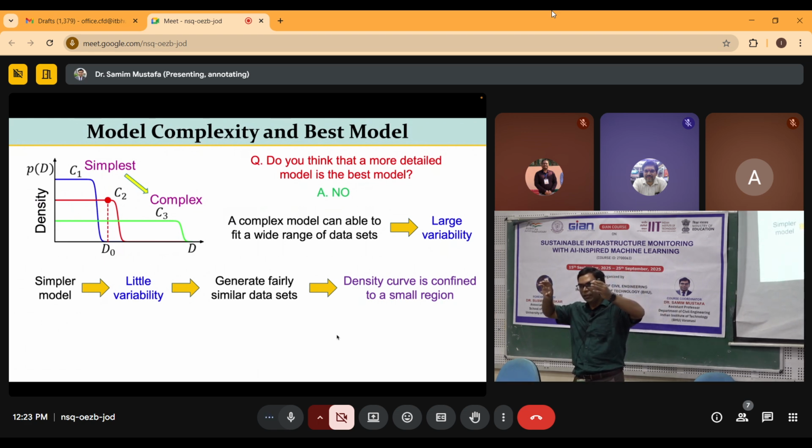So what you will do, you will make your numerical model simpler. Instead of shell element, you can use beam element, or instead of solid element, you can use shell element, depending on your purpose or study, right? I can have a very complex model also, which is needed for probably simulating stresses or some other study related to local response. So you can have a very complex, very accurate model, okay?